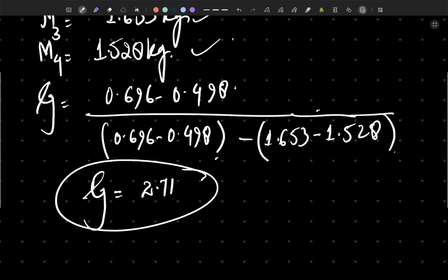So this was how we used the data taken from the gas jar method for the determination of the specific gravity of the soil solid particles, and this method is very much similar to the pycnometer. The only difference is that in this case, the gas jar, which is of about 1 liter capacity, is used, and that is fitted with a rubber bung.